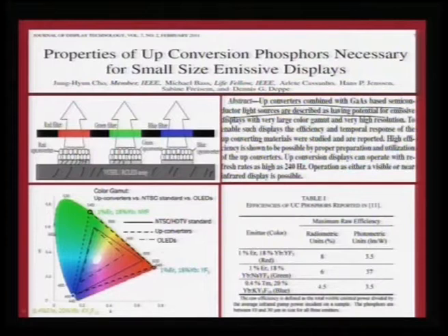But in this set of conversions, you would see the phosphors that are used have a much better gamut of color. For example, the triangle that we see on the outer side corresponds to the up converters that have been engineered here. So, they have a much better gamut of colors compared to OLEDs, which are highly pure, but at the same time have a very limited color resource.